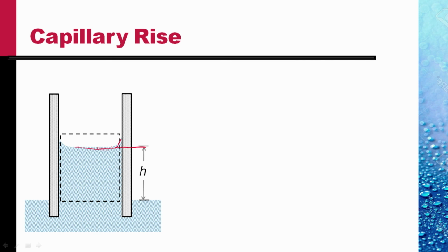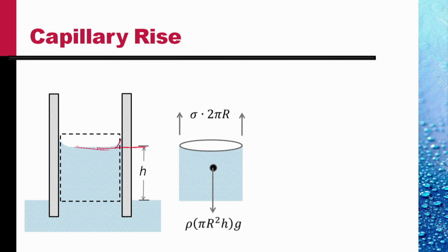We consider the free body of this fluid. This free body is shown here. Clearly, the pressure at this point is the same as the pressure at this point, the same level in a liquid connected with the same fluid. And the pressure here is atmospheric. So the pressure on the top is atmospheric, the pressure on the bottom is atmospheric, and we have not shown it.